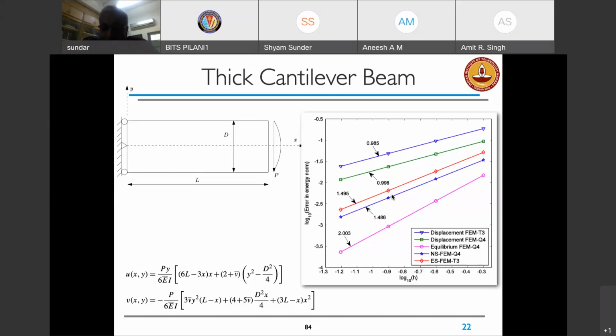So one way to do it is, Abaqus has this nice feature called the user element interface. With user element, you can define your own element. Within that, you can define your own stiffness matrix, shape function, everything. And Abaqus understands it and solves it for you.